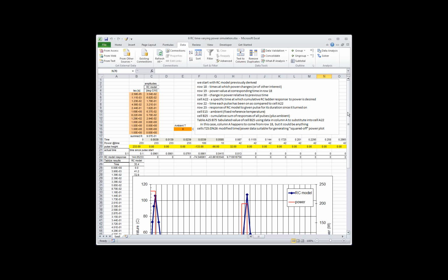Well, the big problem with Cauer networks is that you have to factor that polynomial. The denominator of the transfer function, when you went through the Cauer circuit analysis, gave you a big polynomial, and there are mathematical theorems that show that once you're over fifth order, there are no closed form solutions.